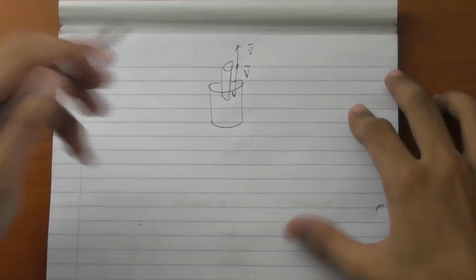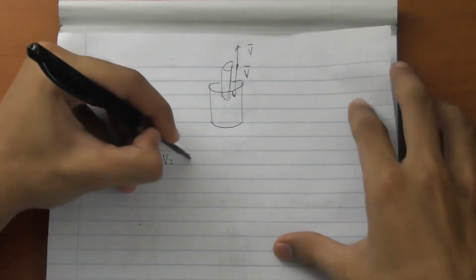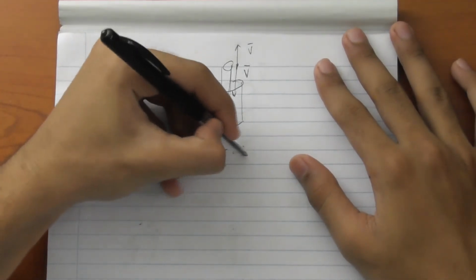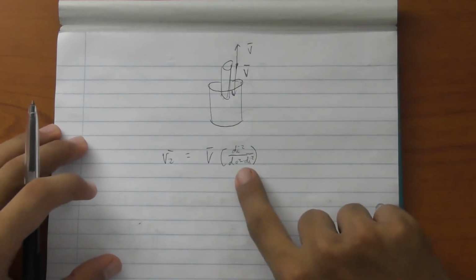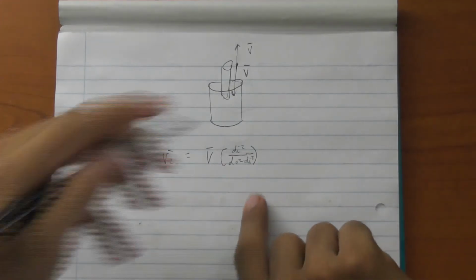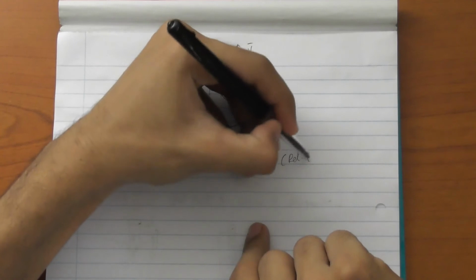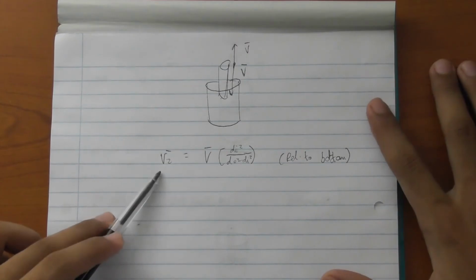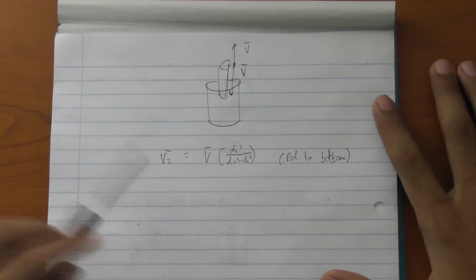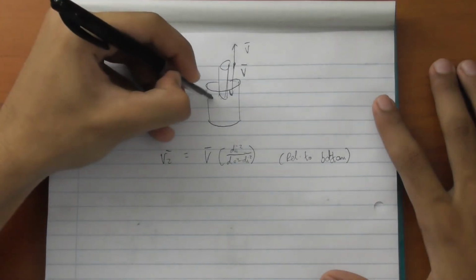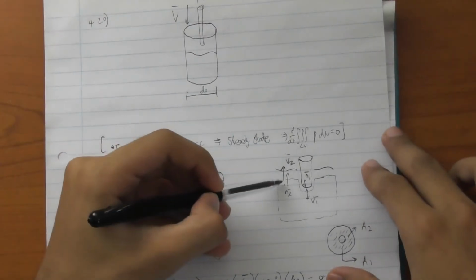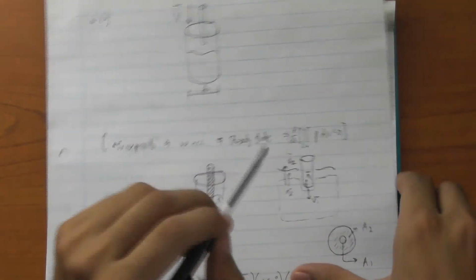So, because in the previous case we calculated v2 is equal to v di squared over d, because we already have this value v2, and that's relative to bottom, then we can say that velocity 2 is the velocity of everything exiting. Remember that? That's how we labeled it on the previous diagram. We said that v2 is everything exiting.